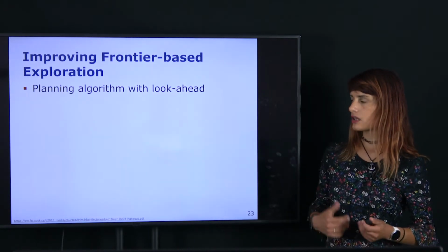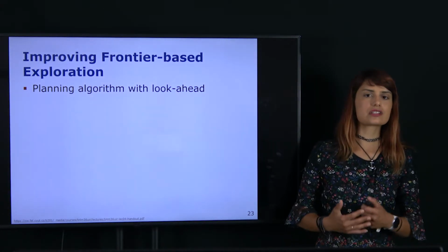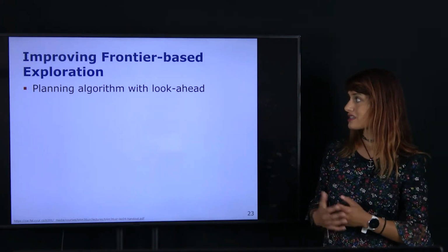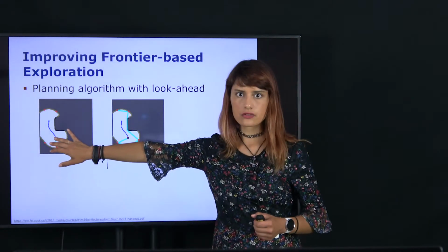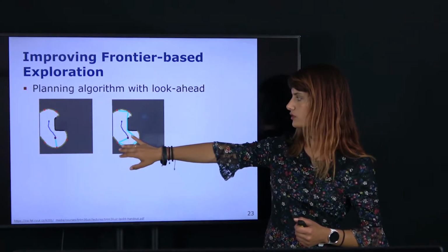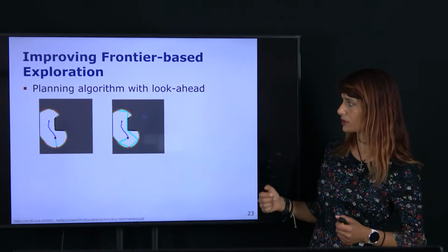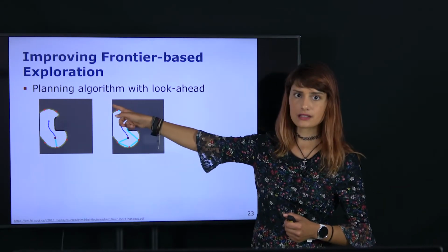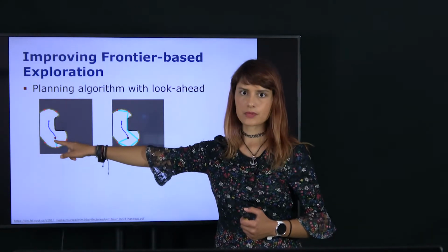Another key element, and an obvious one, is that we use a myopic, greedy exploration strategy, which is susceptible to getting stuck in local minima. And though it is simple to implement, if we have a situation such as this, where we have several frontiers adjacent to each other, it would make sense to plan a tour by considering all the frontier areas at once. So we need an optimization problem that considers multiple possible candidates for generating an actual path, rather than just considering next best view planning.